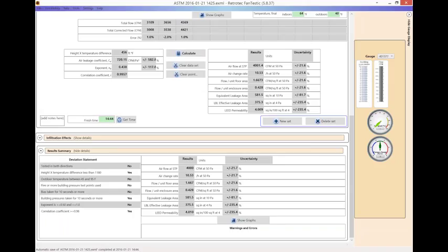All right. So there's a temperature difference and a height ratio from outside. It says you've met that. My outdoor temperature should be between 45 and 95, and it is not. Did I not do enough baselines? I did do my readings at 10 seconds. So whether or not you completely adhere to all of the deviation statements is based upon your test requirements, or the standard you're going to follow with your client, or how you perform this test.